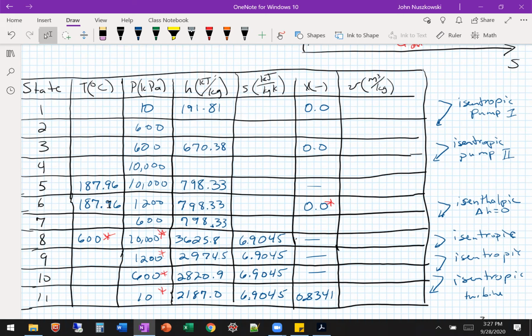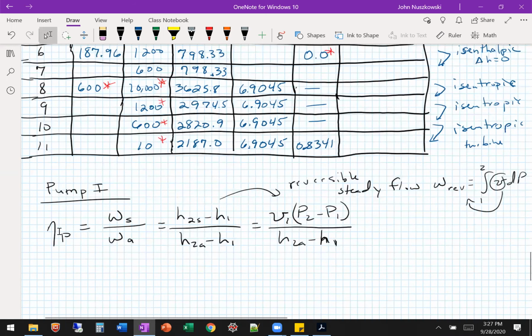If it's an isentropic pump at 1 and 2, right, because we just have an ideal Rankine that didn't give us efficiencies, what does that mean for the isentropic efficiency? Is it just one? Yeah, it's just 100%, right? Or 1, right? So that means it's 1. That's isentropic. So that means H2 actual and H2S are the same. Okay.